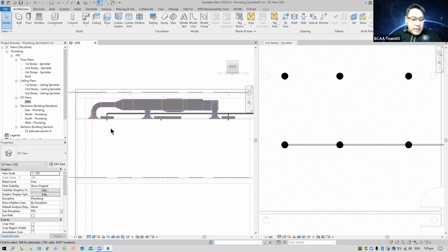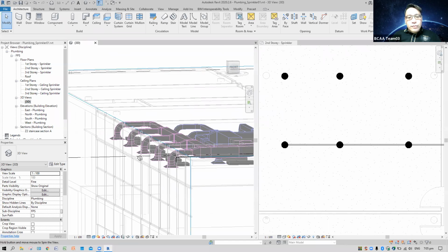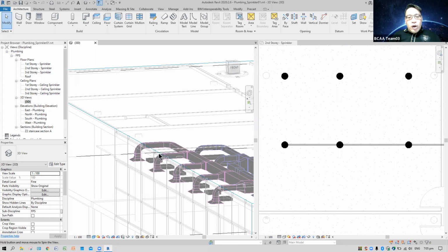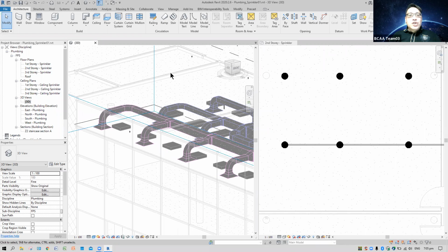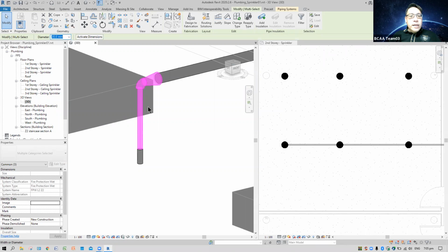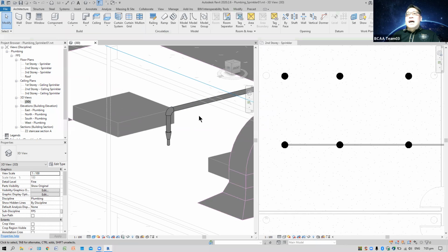As for this particular piece here, what are we going to change? Because when it comes to the connecting point here, it will automatically reduce. So I need to window-select this and change it to 40 mm. Then it will change along. This is a bit troublesome, because it doesn't automatically follow what you specify. It is based on the connecting pipe size. So you have to change it. So in future, just simply copy and paste. If not, every time you generate one by one manually, you really will have a hard time. No joke, fire protection is simple, but the piping is sometimes quite a pain at times.